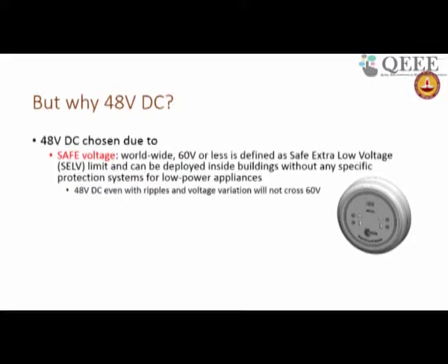A question that I'll just quickly go through, why have we chosen 48 volt DC? And if you see here, I'm also pointing out what kind of connector I have chosen. Look at this. This is a special connector that we have chosen. See this connector. This connector has a horizontal and a vertical. Why? Horizontal is positive, vertical is negative. Remember, it's DC. You can't put it in reverse. And if you didn't choose it carefully, somebody could have put it in reverse. But by using that connector, I am able to manage that well.